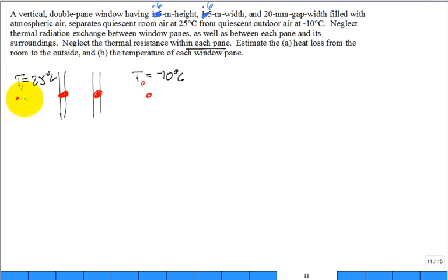So what we have is a resistance to heat transfer, a resistance to heat transfer, and a resistance to heat transfer. We would solve the 1 over h on the inside area and 1 over h on the outside area using the Rayleigh number and the Nusselt number correlation, just like what we did for the previous problem, vertical surface. Even though it's not a knife-edge sharp plate in a large room, it's the best we have. But here, what do we have to do?